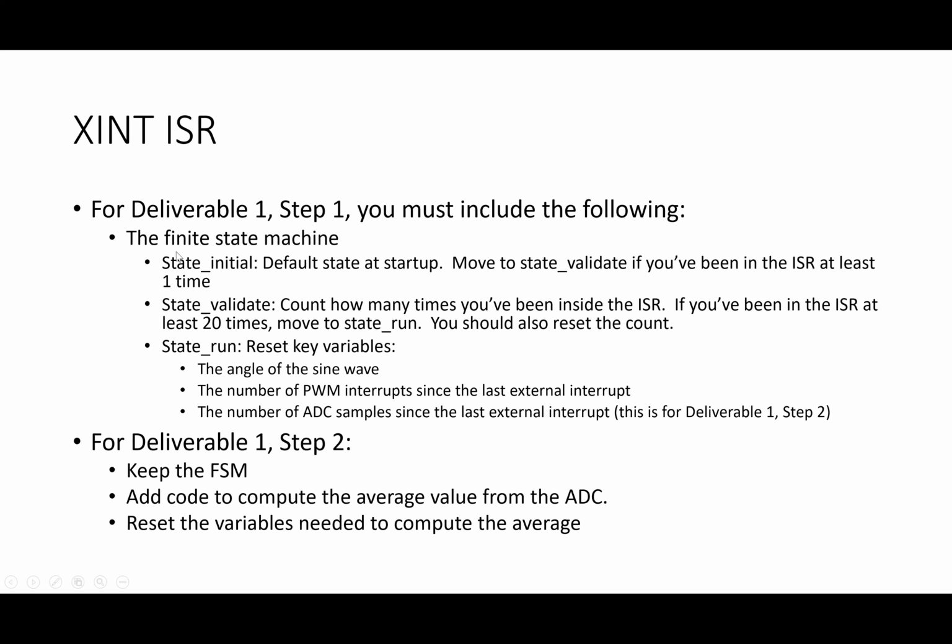The code you need to write really falls into the ISRs. That's where all the code lives for our firmware, inside these interrupt service routines. So from this material, you should be able to get going on writing your firmware, or completing the firmware that you may have already started. That should help. Now, there'll be a couple of additional videos that talk about how to calibrate the ADCs. That's the only other real item that we need to worry about.